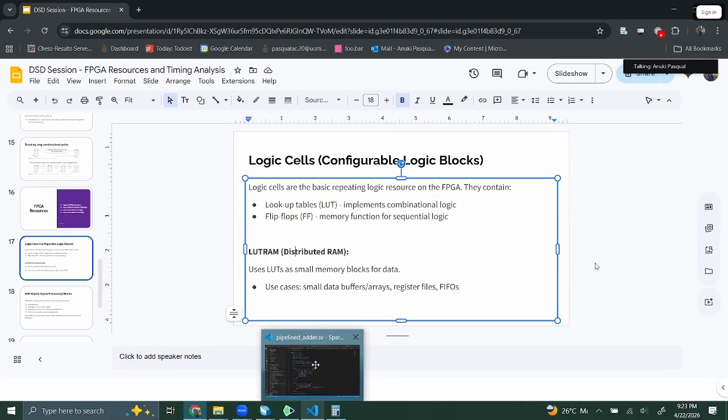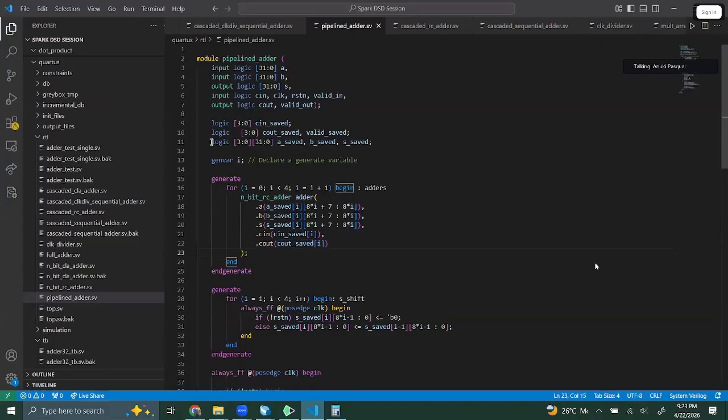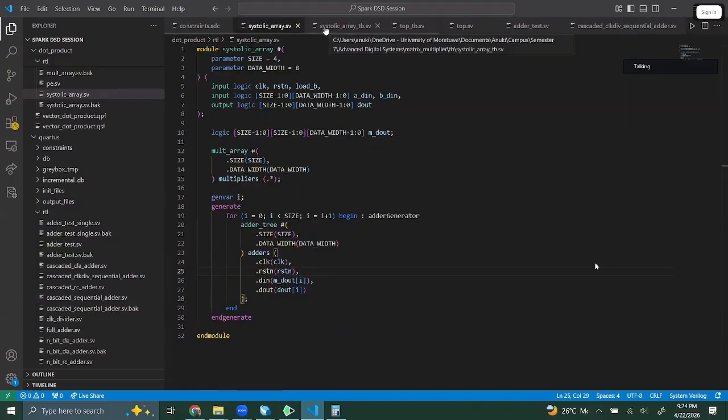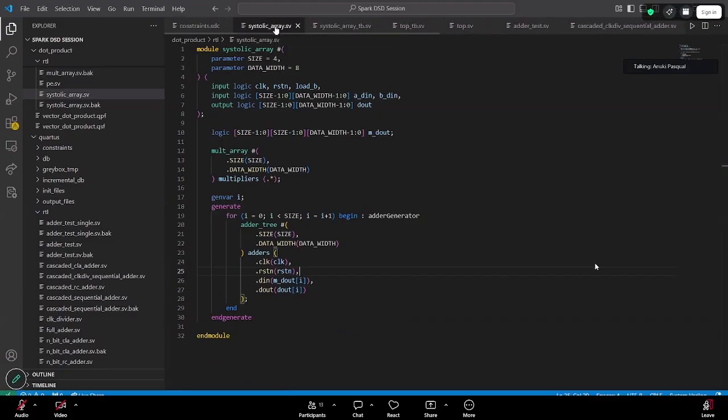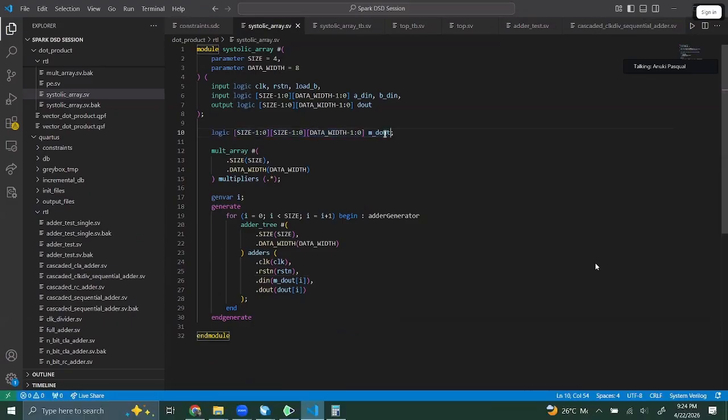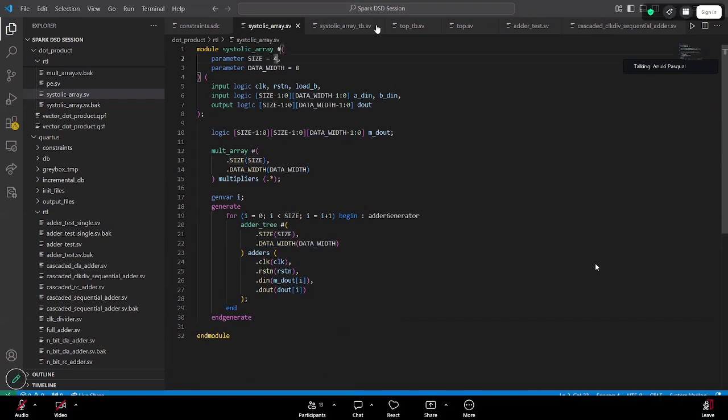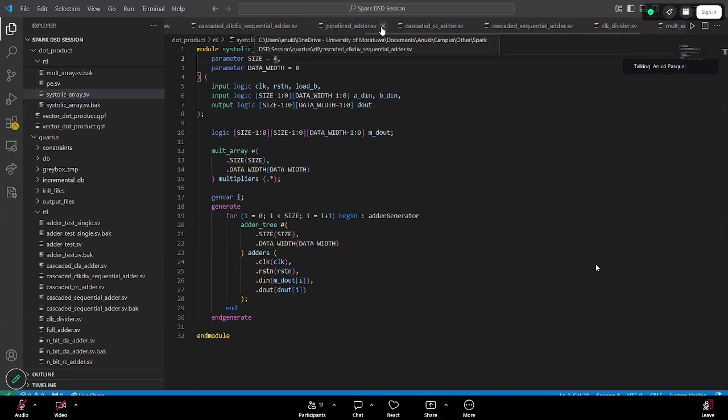If you don't specify anything special. Yeah, this is a different design. This is a multi-dimensional array defined in Verilog. If you define something like this with a larger size, like maybe 60, it might be synthesized as a LUTRAM.